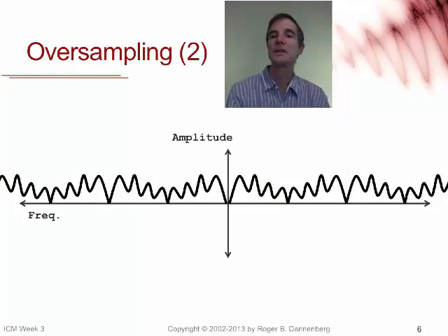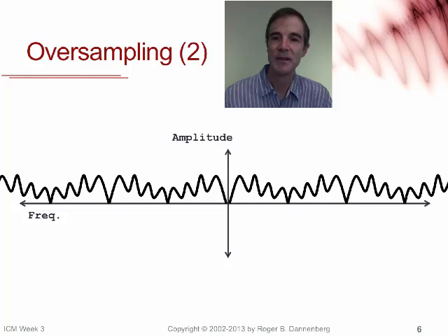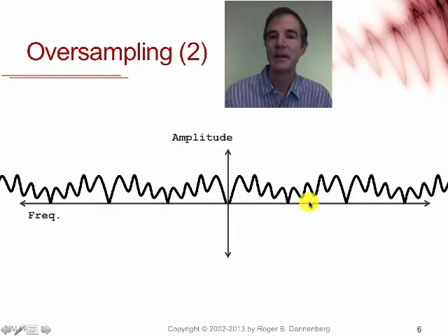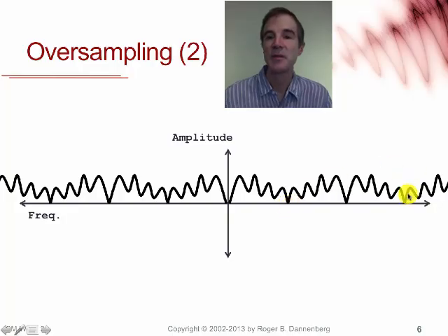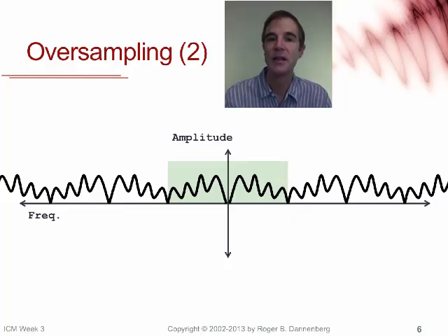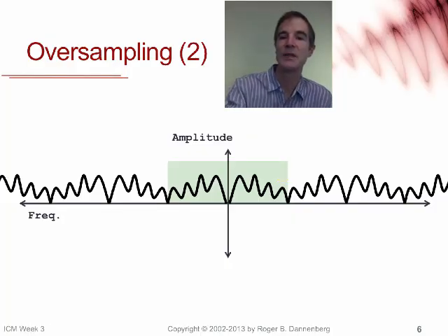So here's how this works. Suppose this is the signal represented by our digital samples. So here's the Nyquist frequency right here, and here. So we have a full spectrum signal, and of course, since it's sampled, the spectrum repeats with an offset of the sample rate. So our goal, if we were building an analog filter, would be to extract just the spectrum up to the Nyquist frequency.